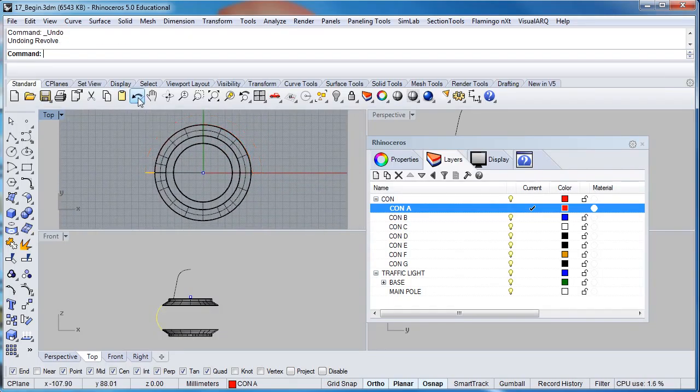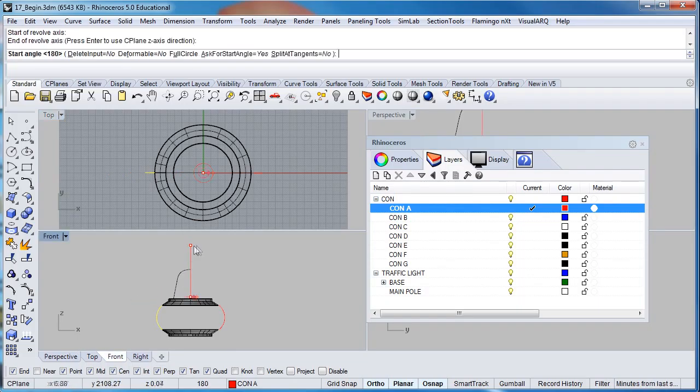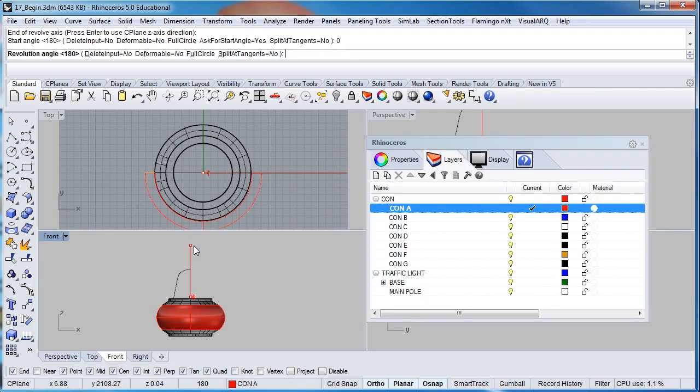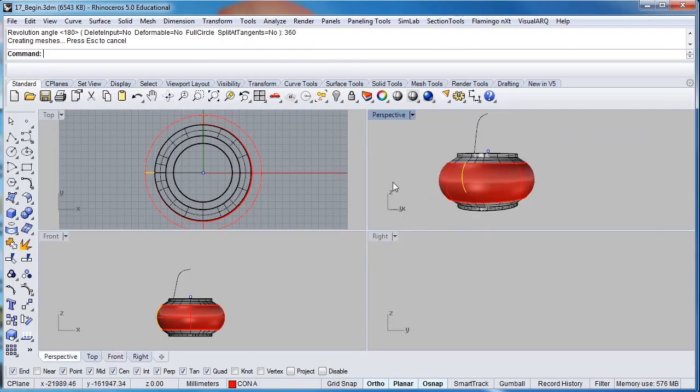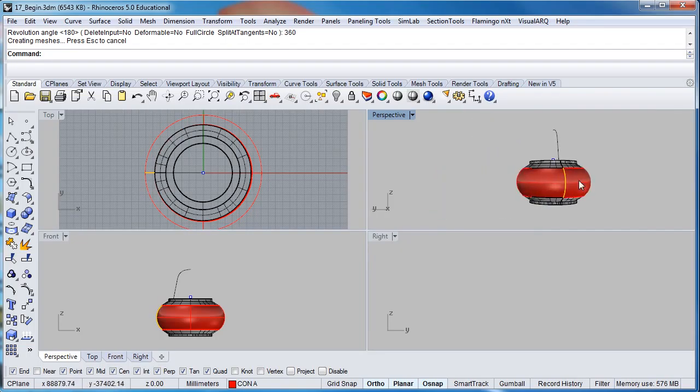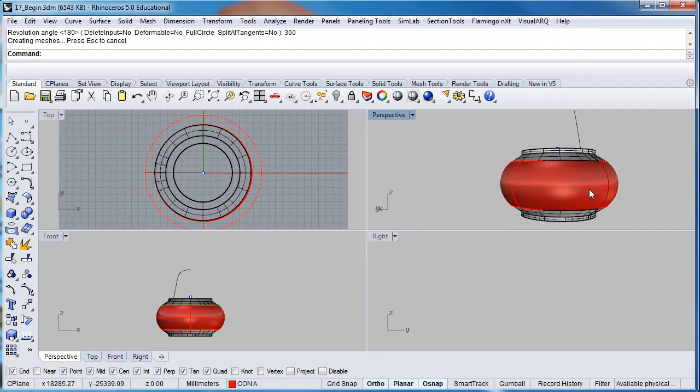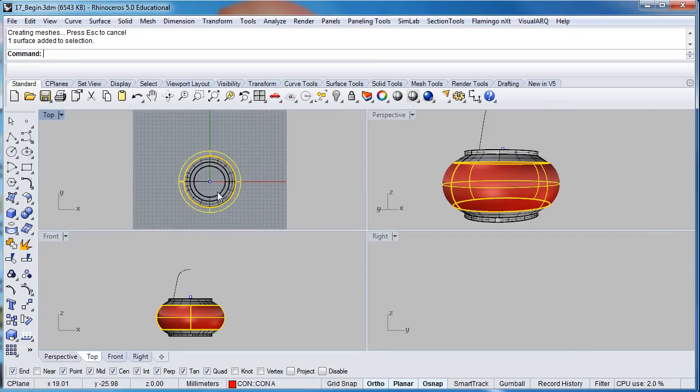We're just going to change those defaults one more time. So right click, start axis, okay, end axis. The start angle is 0, so we're just going to put that in there now. So 0, enter. The end axis is 360. I'm just keying that information in so you can see we've rectified that. I'm just going to close the layer manager so you can see that. So we've now put in, instead of a 180 degree section, a 360 degree section through there.